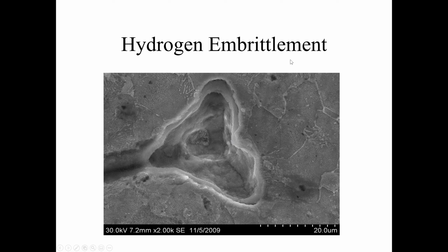What happens is when you weld or manufacture steel or use steel, if it's high carbon steel, some hydrogen will diffuse into the steel. The hydrogen reacts with the carbon in the steel and forms methane. Eventually the methane starts to expand and pop, and a bubble pops. It induces these cracks and failures inside the material. Then the cracks start to grow, and eventually the whole material will fail.